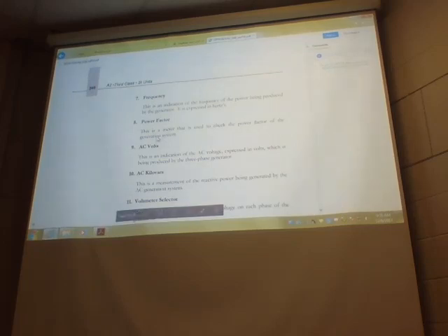So you monitor it, and see if there's some way of correcting it with capacitors or the motor that you can use as power factor correction. A synchronous motor, when it's used to correct power factor, is called a synchronous condenser. A is your power factor here.